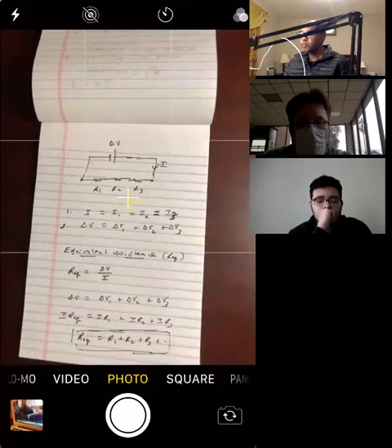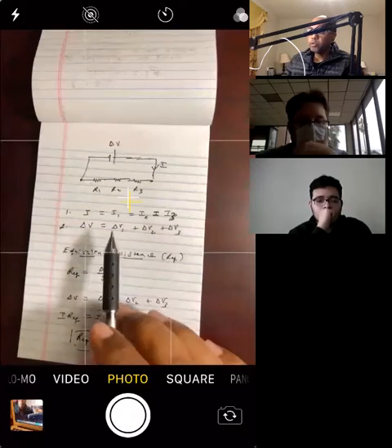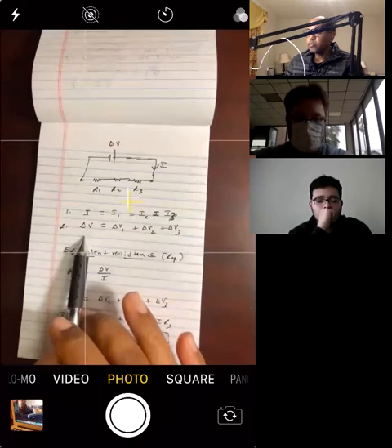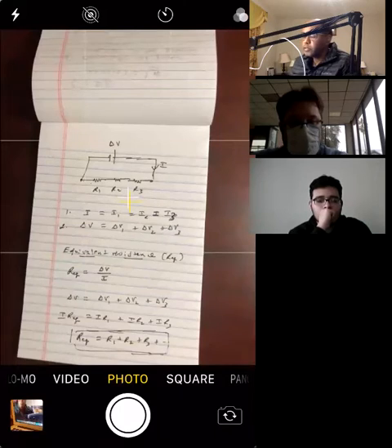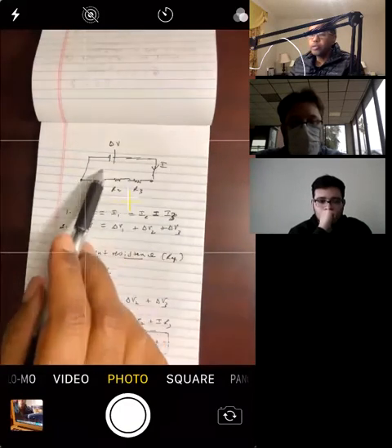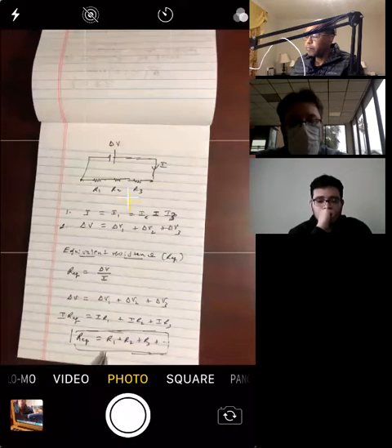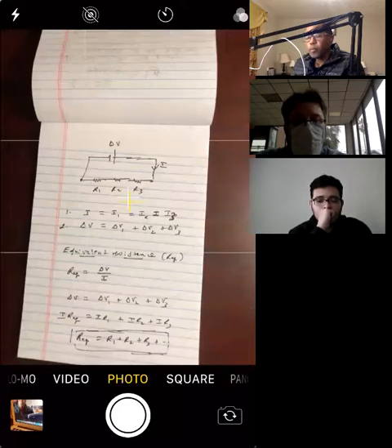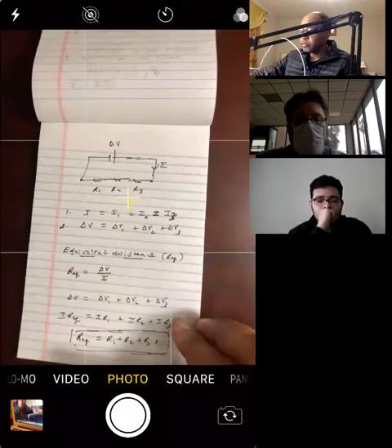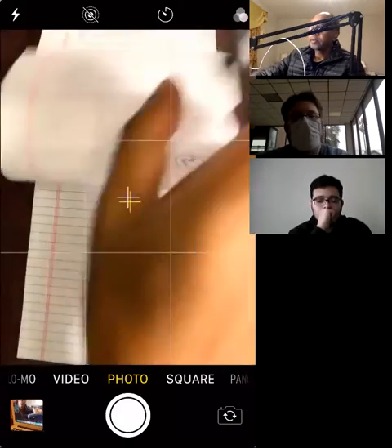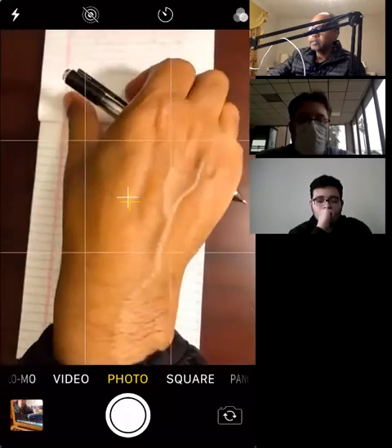All right. So the most important thing over here is that for a series combination, all the currents are equal, and the total potential difference is the sum of the potential differences across the individual resistors. Okay, and the single resistance that can replace the combination without changing anything is obtained just by adding the resistances. Now you remember the formula for capacitors. For capacitors, this was for parallel. Okay, so they flip. For parallel capacitors, you add them, but in this case, for resistors in series, you add them. So the two formulas flip for capacitors and resistors. All right. Let's look at an example.